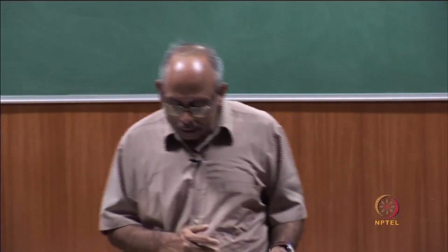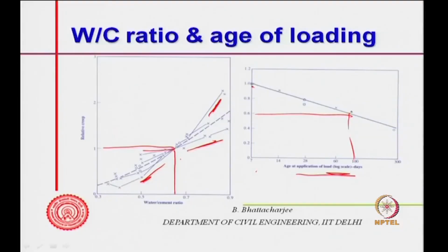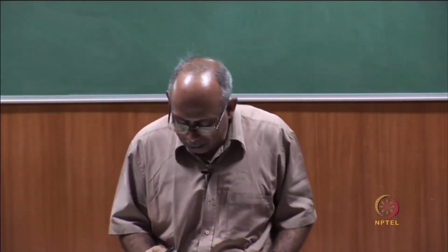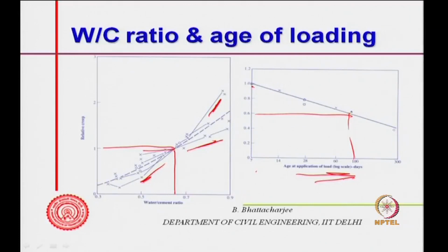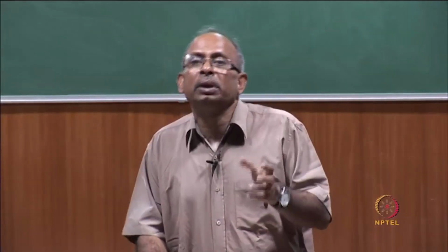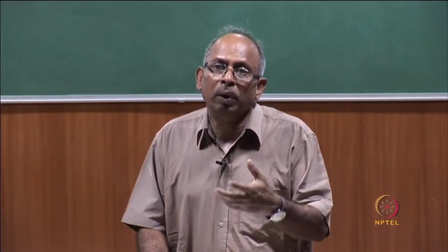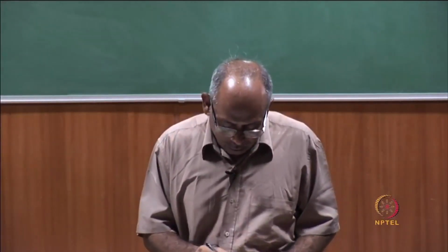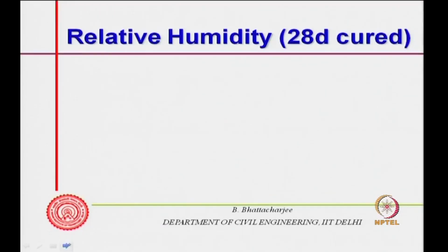Now, this same thing follows as hydration progresses. Obviously, the gel structure or segmentation occurs and the gel structure becomes very solid. So, if you apply load later, you are likely to find less creep, because you are applying load in a system which is more matured. So, therefore, you are likely to find less relative creep, as shown here. What about relative humidity?